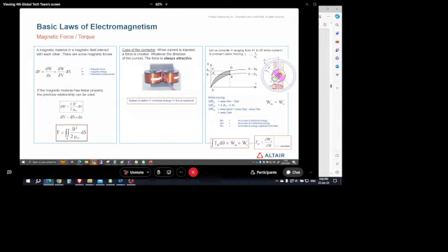So in this position, this is the stable, the balanced position, where we maximize the magnetic flux and we minimize the energy. Then, if I move it to a given position, I will feel that there is torque. The movement will create the magnetic energy variation, and then will create the force and then the torque.